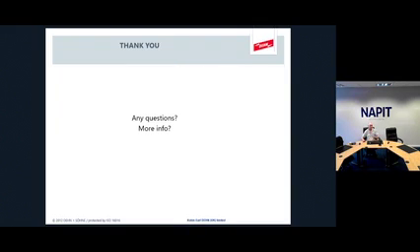So as an introduction then to 443 and 534, I think the key takeout message is on the risk assessment. There are certainly a set of values or types of installation where you cannot afford to leave out the SPD. That's going to be human safety, public service, commercial activity, and a large number of co-located individuals.